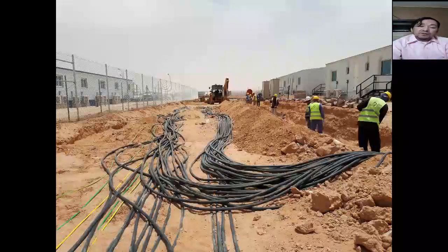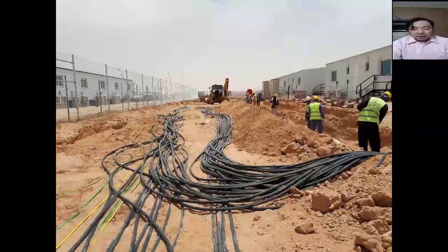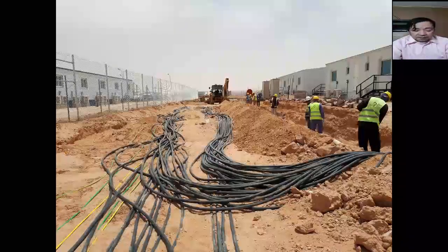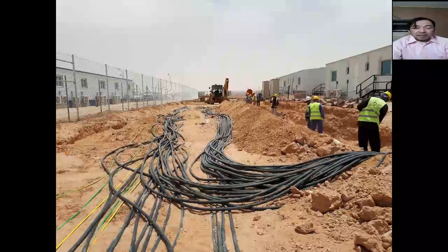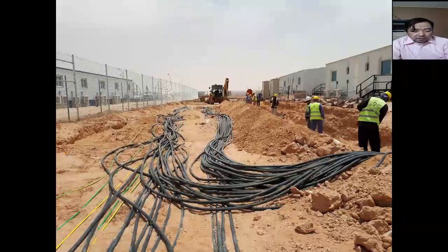In case you need an even lesser depth, you can use B: PVC coated RGS with a total cover of not less than 150 millimeters, which includes a 100 millimeter thick reinforced concrete slab over the conduit.